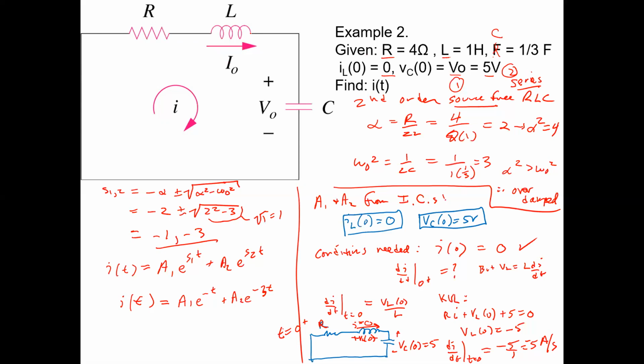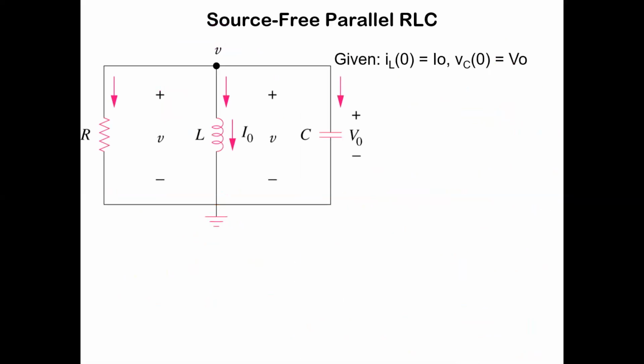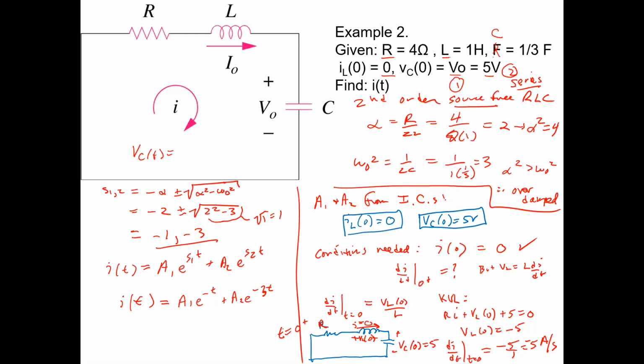No, I is flowing into the plus side of the capacitor, right? Well, if we're calling this V0 as VC, right? So VC of t is going to equal V0, right, plus the integral of I dt over C, right?